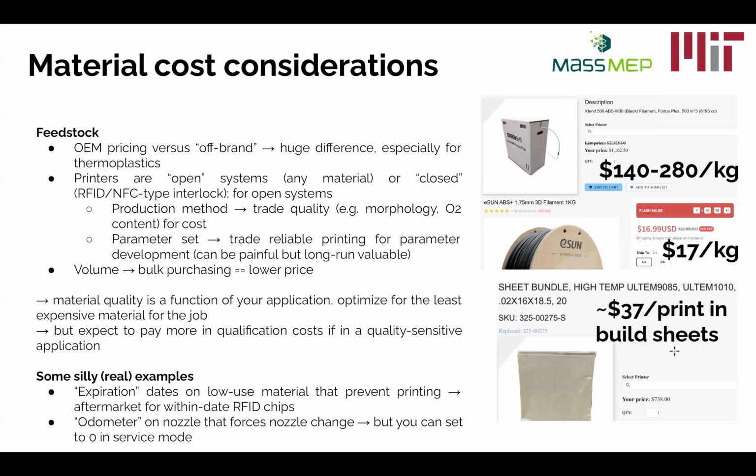So if I want to get the best bang for my buck, and this is going to be true for all additive processes generally, I want to load as many parts into the build as I can reasonably get away with, because there are going to be fixed costs simply with pressing print, irrespective of how much material I'm using, and I want to be optimal in that way.